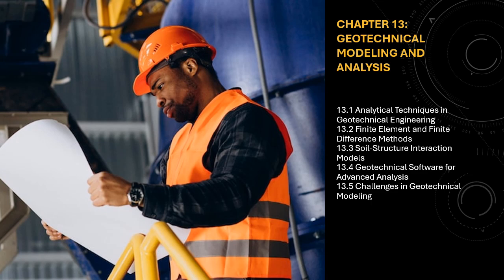Mitigation: incorporating site-specific data from geotechnical investigations, borehole data, field tests, laboratory tests, and employing stochastic modeling techniques can help represent soil heterogeneity more effectively. In some cases, using random field theory and Monte Carlo simulations can help account for soil variability and improve model predictions.